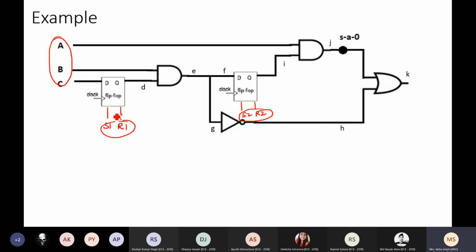So the number of inputs will be very, very high if I consider any general practical circuit. Right now there are only 2 flip flops, so 4 inputs increased. If I have n flip flops, the total number of inputs is increased by 4n, where n is quite a large number in practical circuits. Right? Each D flip flop represents 1 bit. Right now we even have 64-bit processors. So the number of bits is very, very high, so the number of flip flops will increase and hence the number of control inputs.